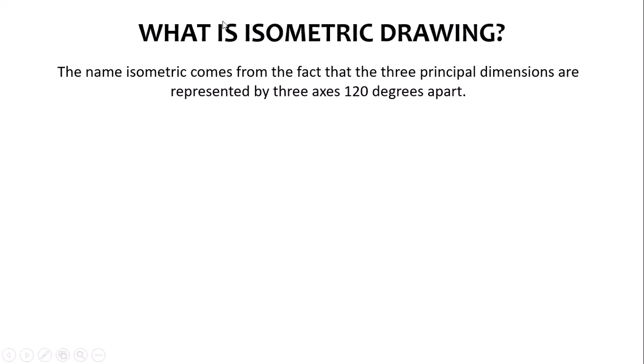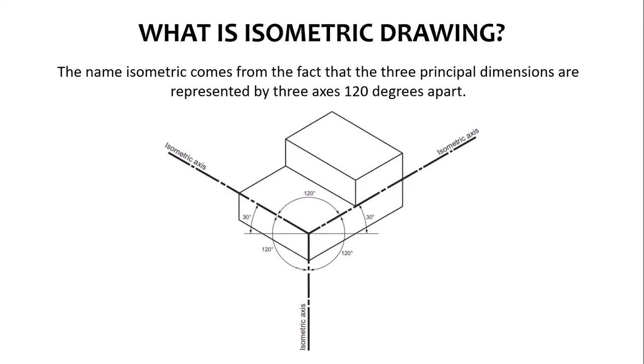Now for isometric, the ISO just means that the principal axes are 120 degrees apart. If you attended the first meeting, you obviously heard me not talking about this 120. Instead, I like talking about the 30 degrees because it's the much more useful angle. So in that tutorial, I talked about two angles that are always equal that are used to get the isometric axes.